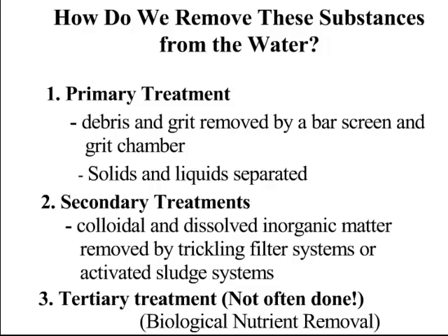Right after that, the sewage is going to go into a big holding chamber. It looks just like a very large swimming pool, and it's just going to sit there. And this will allow the solid parts of the sewage to sink down to the bottom of the tank and be separated out from the liquids. It also is going to allow fats and oils to float to the surface and be scraped off. So what we'd be left with is just a liquid waste.